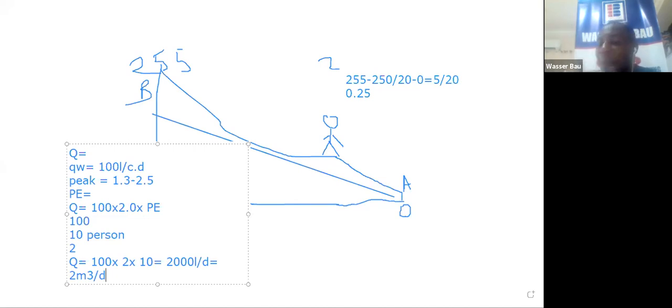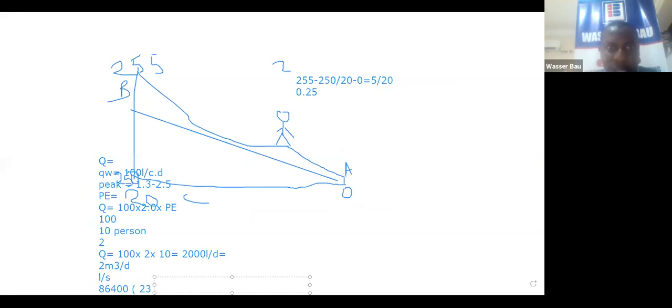But when you now want to design the pipe, you have to convert this into liters per second. To convert to liters per second, remember, you have to divide by 86400. And why do I get 86400? 1 day is 24 hours. Stay with me, please. In 1 day, we have 24 hours.